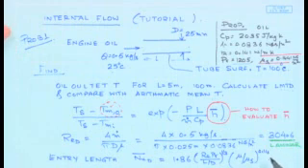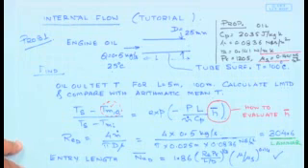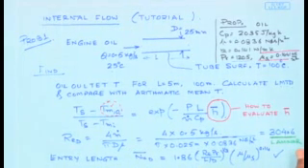So, a Sieder-Tate equation which takes into account the variation of viscosity between the bulk and the tube wall temperature, that Sieder-Tate correlation is modified for when we have to consider entry length as well. So, this is the relation which we are going to use. I know the value of Reynolds number, the value of Prandtl number is provided in here. The length is either 5 or 100. The diameter, the values of viscosity are provided. So, from here I can calculate what is the Nusselt number, and from Nusselt number I should be able to obtain what is the value of the convective heat transfer coefficient.